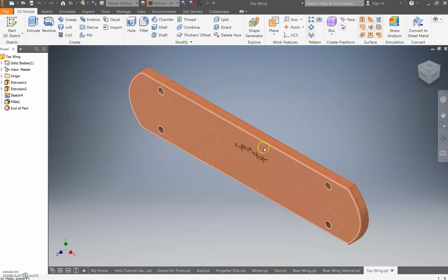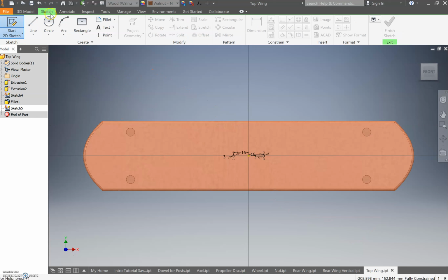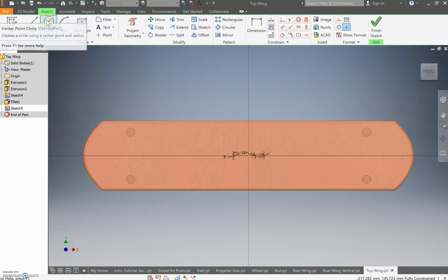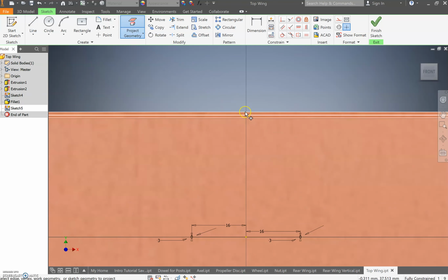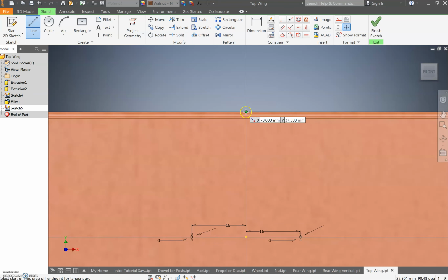To go through, we want to continue though. We want to add this nice little semicircle coming out of there. You go Sketch, come here, select on that. This is where we need to be quite intentional about how we draw this. We're going to start off with projecting. I'm going to come all the way to the outside line, and you're going to project that line there. That is very important. From there, go to the center point of that outline, and it'll stop halfway because it's halfway along.